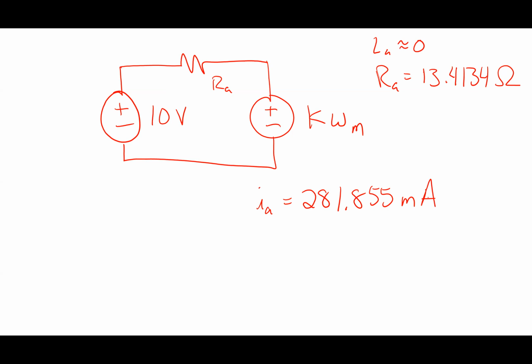It's really pretty straightforward to do these problems because they're DC. This is circuits 1 analysis to really do this, right? The question that I asked there in the homework: what's the torque that this machine is making? So it's hooked up to a load. I got 10 volts hooked up to it. What's the torque that it's making? K times IA. All right. So whatever load it's operating against is requiring K times IA.